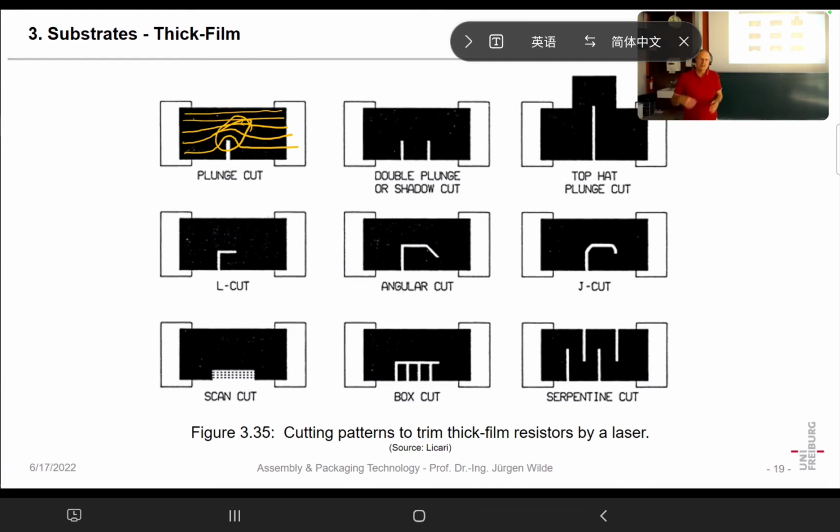But again, it shows us we always have to take into account how the material reacts. We have a dependency of temperature on current density. Again, if it's hotter, also resistance will be increased. That will still increase temperature locally. And so in that way, these are effects which have to be taken into account.